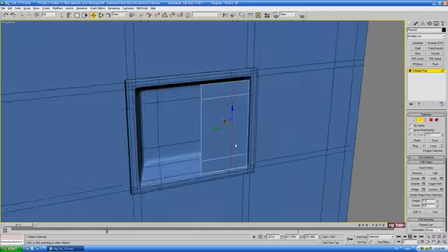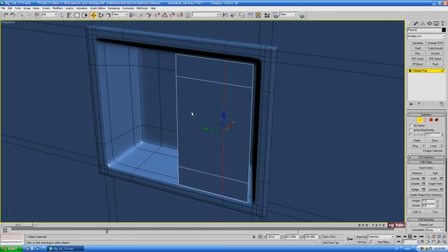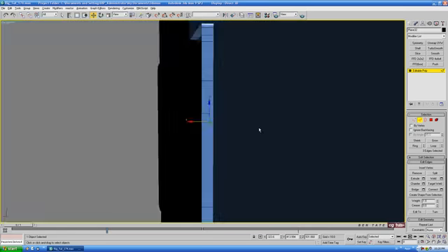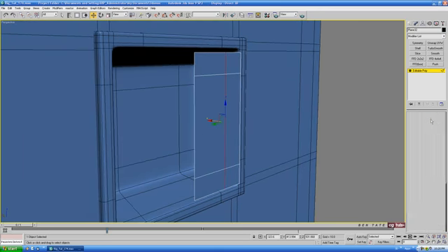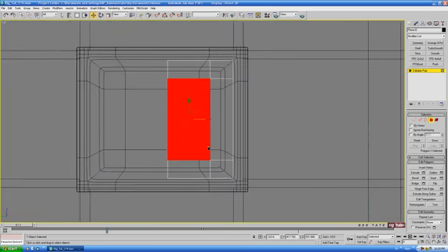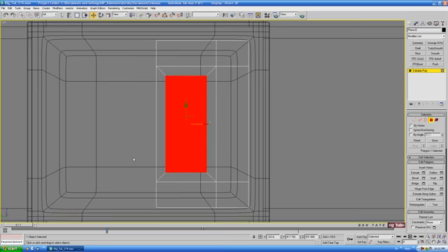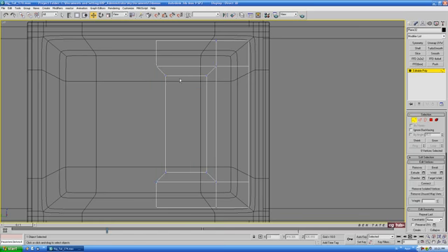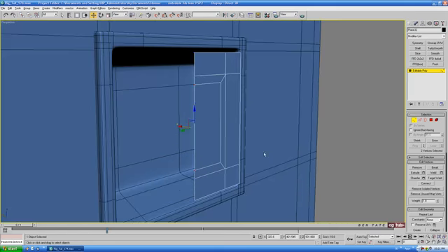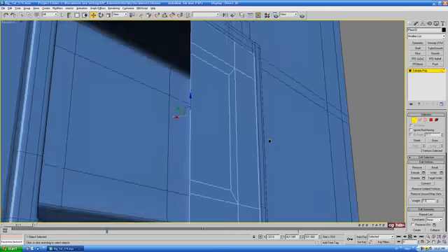And we want to kind of extrude or bend the surface out here, so we got kind of like a little bit of a handle. Let's maybe go to polygon and grab that polygon there, and we'll do an inset on this one. Let's take it up a little bit more. Let's do about 1.2 or so, and okay. And let's maybe grab this left polygon here, we'll delete it. We'll go back to vertex, we'll grab these 2 verts here, and we'll just pull those over and straighten out the edge. Okay, like that.